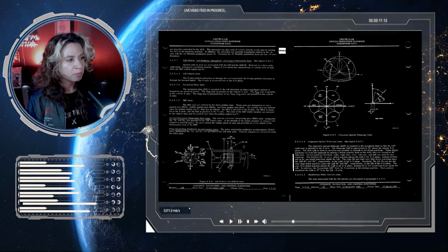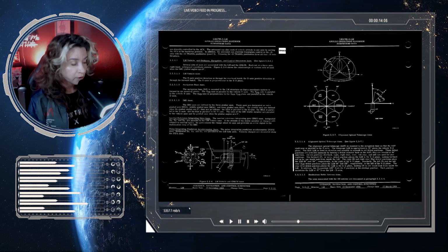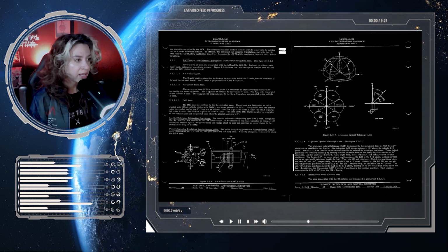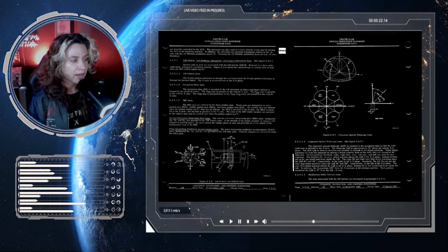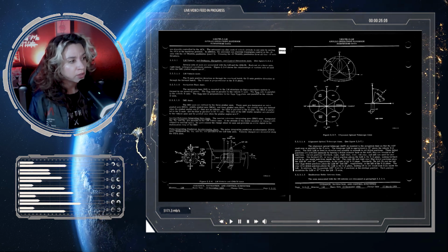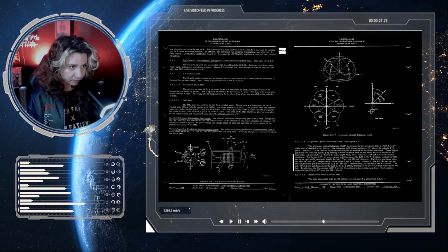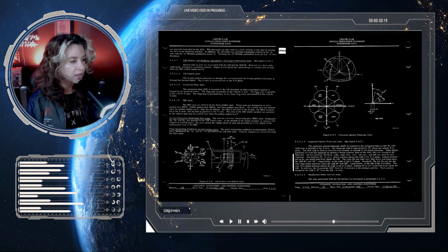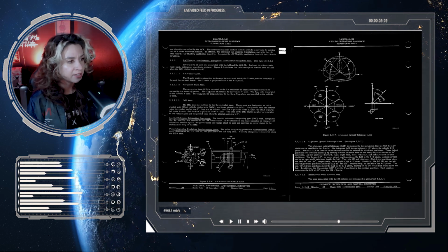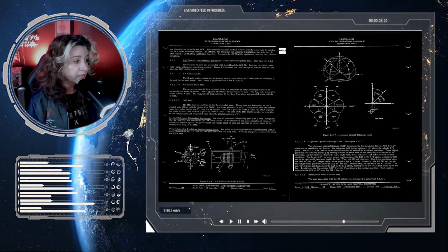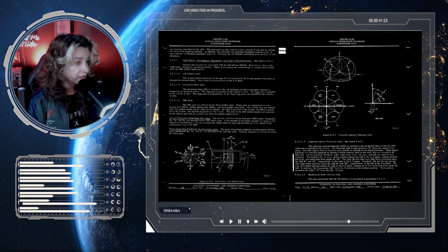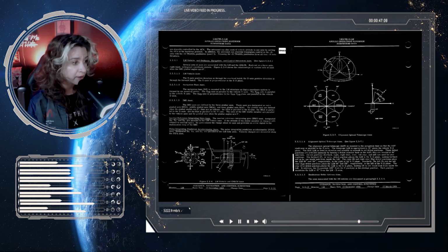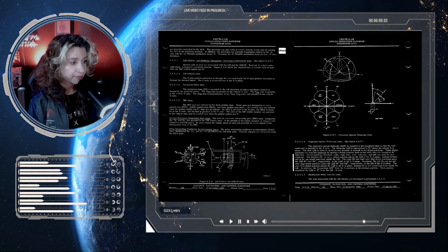The pulse integration pendulous accelerometer, or the PIPA, axes, designated XA, YA, and ZA, are parallel to the LM body axes. Velocity changes are measured along the PIPA axes. Okay, below you will see figure 2.2-6. This is the LM vehicle and the GN&CS axes, and it has a breakdown of basically everything that we just spoke about as to where the designated axes are located in the LM.